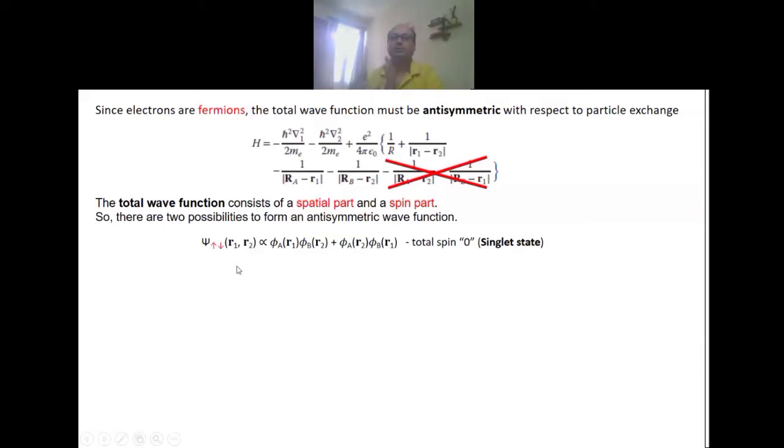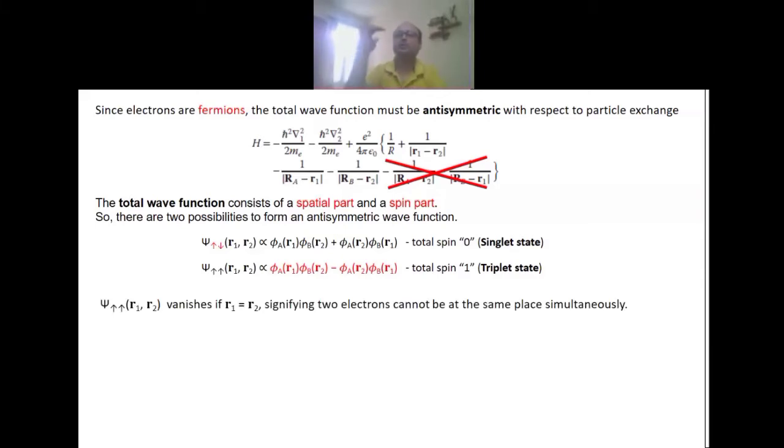What you can see is that in the metal you do not have any band gap, so the bands actually overlap. This dotted line you can see is called the Fermi level, where you get the density of states, meaning your electrons will be populated up to the Fermi level. But in a semiconductor, you have a gap. The Fermi level is not completely enriched with electrons. In an insulator, the gap is so big that there is a long distance between your Fermi level and the valence band maximum, where your maximum electrons can stay.